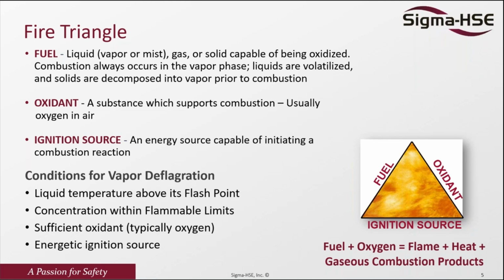I need to know whether I have oxygen to support flame propagation. Then I also need an ignition source, something which is supposed to initiate the combustion operation. The ignition source could be electrostatic discharge. That is the topic for today. We could also consider hot surfaces, arcs from electrical equipment, maybe overheating of bearings. These are the various types of ignition source that need to be considered.